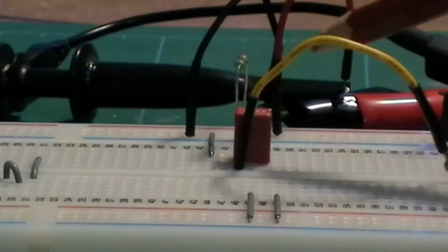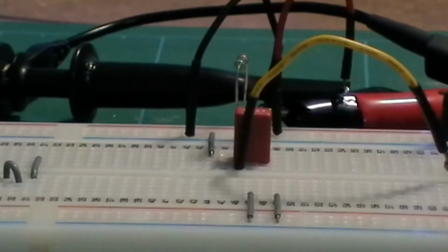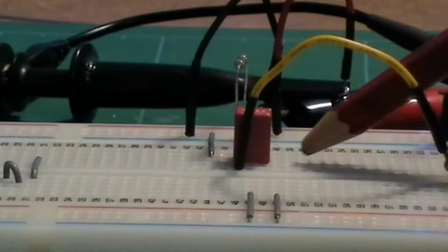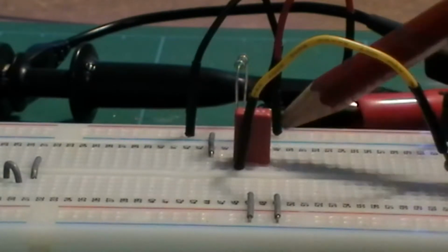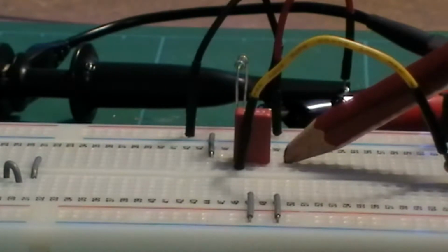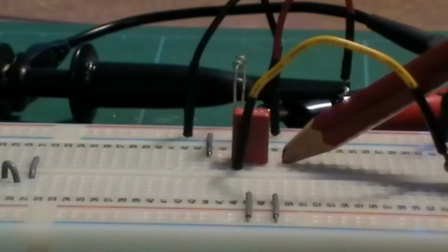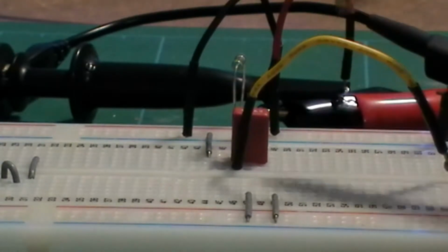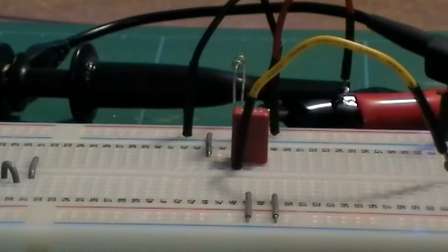Now, I've decided to go with the same capacitance as I did with the low pass filter. I'm going to have a 1 microfarad, a 220 nanofarad, 100 nanofarad, a 47 nanofarad and a 15 nanofarad capacitor in there, and I'm going to see what frequency cutoff point I'm going to get and how it affects what I'm going to get through. So starting with the 1 microfarad,